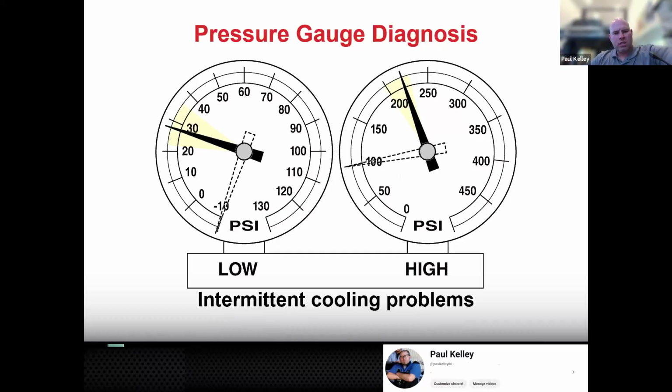Ooh, this one was interesting. We had a really similar one with Chris's mom's Camry. You fire it up, you get 200, maybe 215 on the high, 28 on the low, but then all of a sudden, boom, it's minus 10 and 100. The AC starts to blow warm, but then all of a sudden it goes back to 200 and 30.